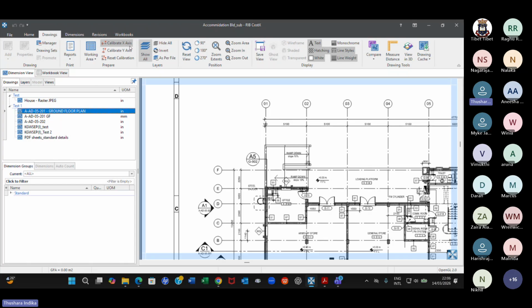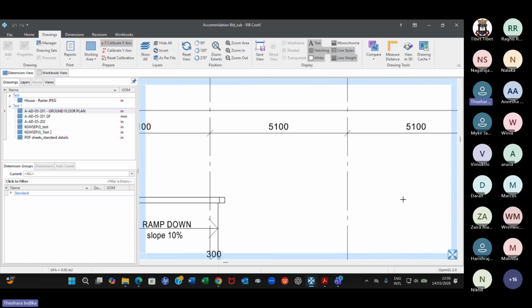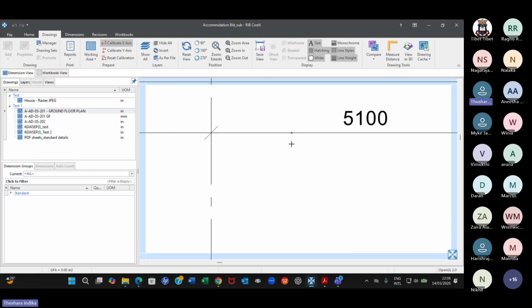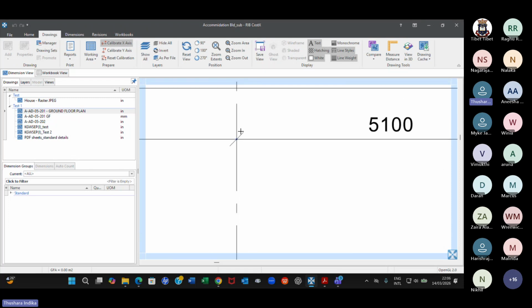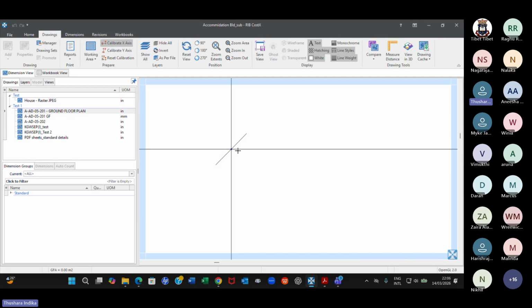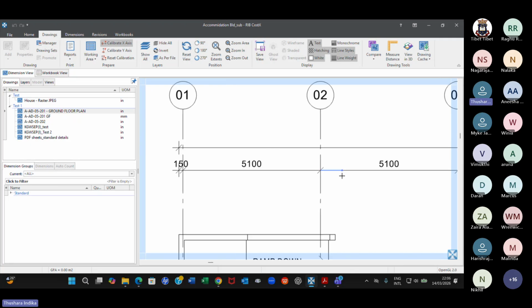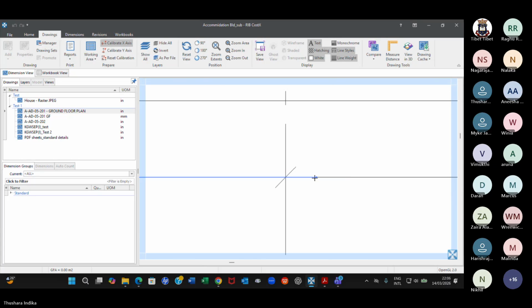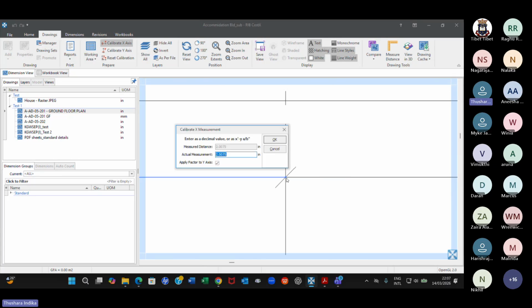I'm going to calibrate the x-axis similar to what we have done. Now in the PDF, selecting the point is a little tricky, because we all know it's a kind of image at the end of the day. It's not very accurate like AutoCAD, but here it is accurate enough. So you click on this and then on this. Now you can see it is ridiculous again. Again in inches. So probably I made a mistake there. When I first introduced this, I made it in inches.